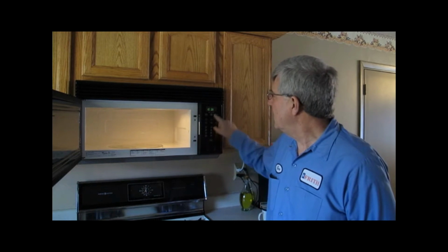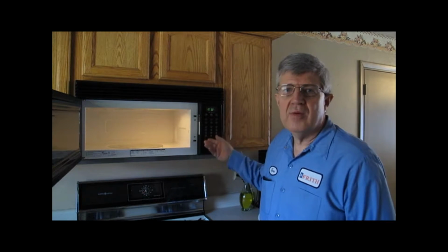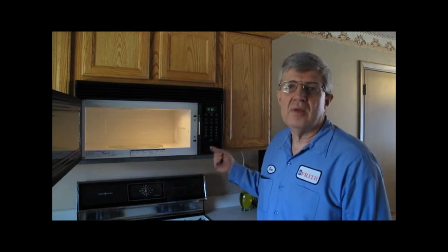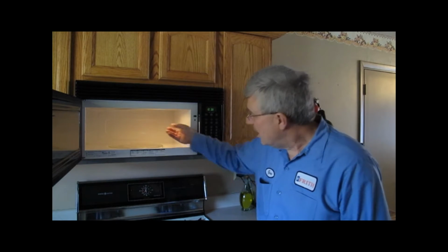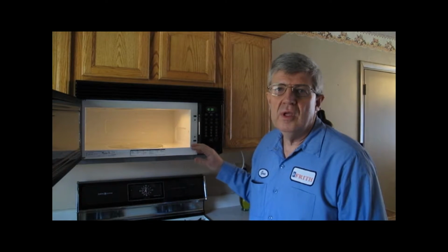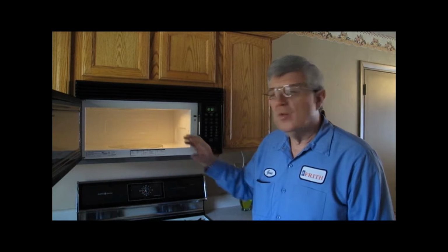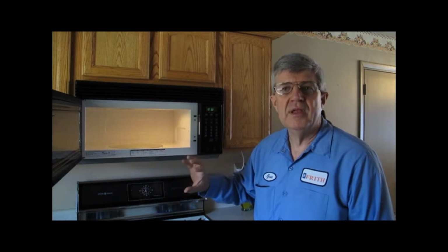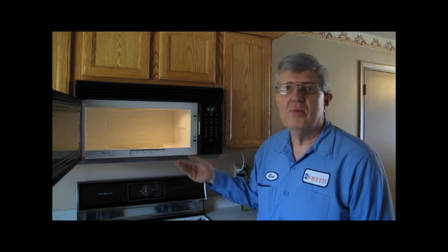And these are generated by the magnetron tube, and it sits behind here. And when you start the microwave up, you might hear a low humming noise. So that's a thing that emits the electromagnetic radiation, or again, radio waves. They come out here, and they come out at a frequency of 2.45 billion times a second. In other words, they're oscillating, they're going back and forth, changing direction 2.45 billion times a second. And you'll see in a minute why that's important.